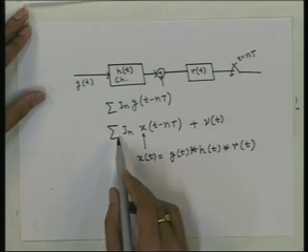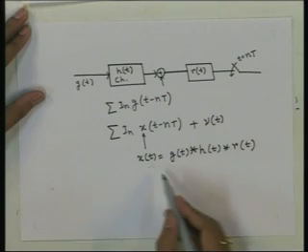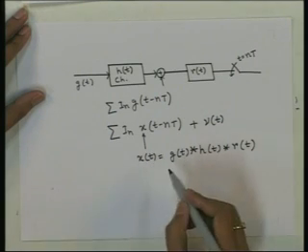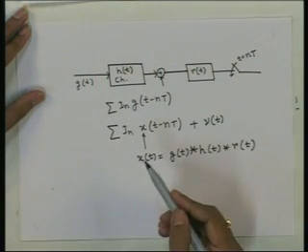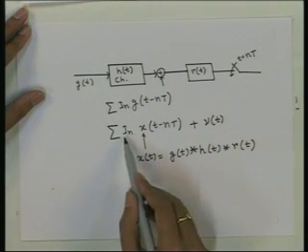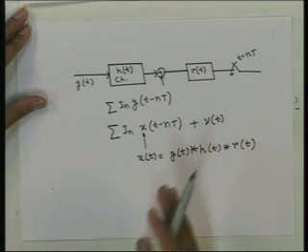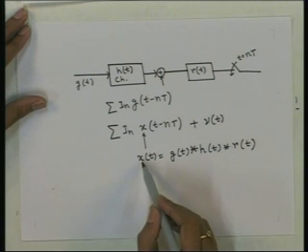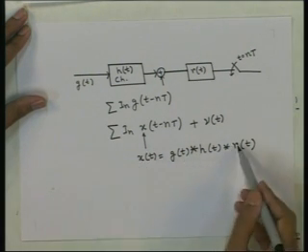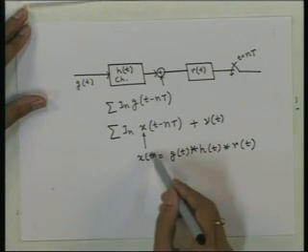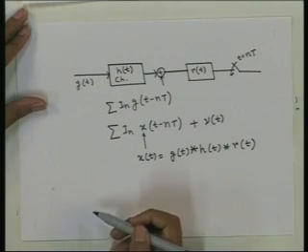So, when we sample this signal every capital T seconds, at the nth sample we will not only get I_n, we may also get some contribution of the other symbols if x(t) is not chosen properly, that is if g(t) and r(t) are not chosen properly to have x(t) satisfying certain conditions.